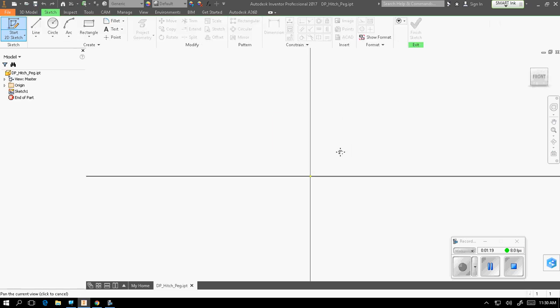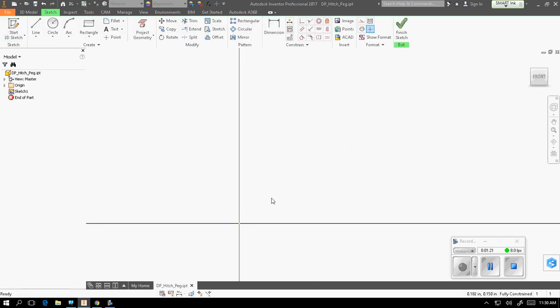As you can see, I changed the color, and I'm hoping that this gets rid of that blurry background that we had in the body. So we're going to take a line, and we're going to go here, start on the axis first, here, here. Then I hit escape to get out of that line command, and then I'm going back, and I'm going to make that. Okay? I didn't do the arc yet. I'm going to wait, and I'm going to dimension everything first, and I'm going to add the arc last.